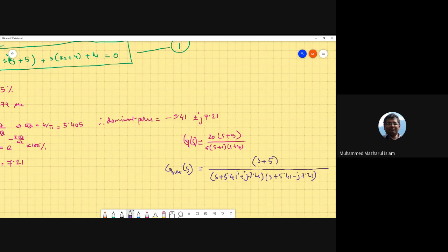Up until now, we have gotten up to this point. For the third pole, if we didn't have any zeros, we could place it at maybe minus 27 or minus 30. Because we have a zero, let's place it at minus 5. Therefore, it would cancel the zero out, and my modified system, my control system, will behave exactly like a second order. This is important because the system's performance will be exactly like I intended.